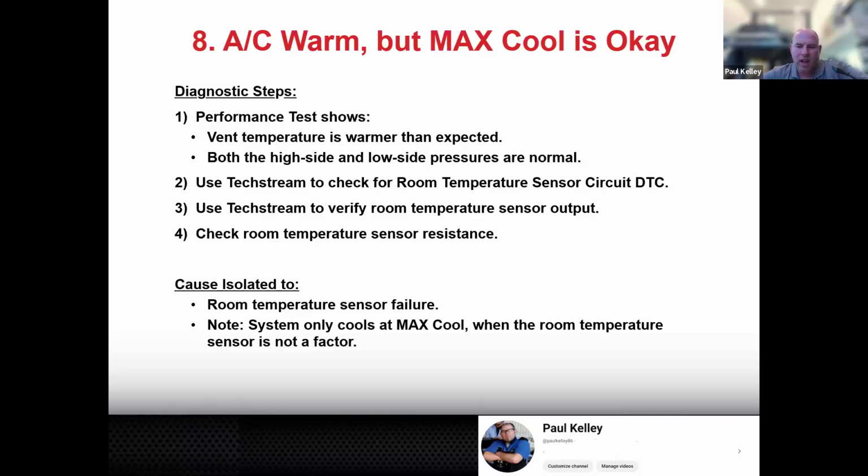So you'd be like, oh, it's 65. How many ohms should it have? And then you'd measure it, right? And if the thermistor itself is out of spec, remember I was talking about this with my refrigerator. If the thermistor itself is out of spec, then boom, you're getting a new temperature sensor. But if the thermistor is in spec, it's possible you could have resistance in the circuit somewhere if it's reading too low. So that could be like a connector, a wire, you know, the terminal type of thing. So yeah, that would be an excellent idea. All right, how about this?